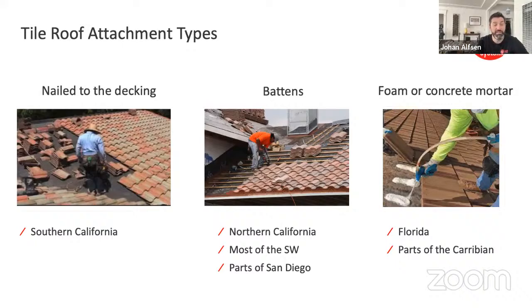And then in Florida, they have a lot of adhered tiles. So this makes things a lot more difficult for removing a tile, because in some of these higher wind areas, like where you have Dade County regulations, they will glue down every single tile instead of nailing it. So they're either mortared in or foamed in. You can see there they're spraying down an adhesive foam, and then his partner up above is laying down the tile and locking it in so that it can withstand those really high wind speeds.